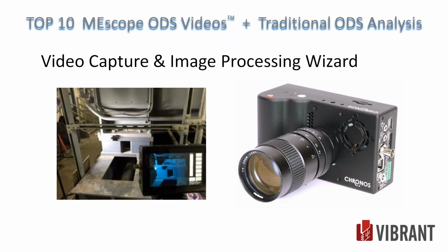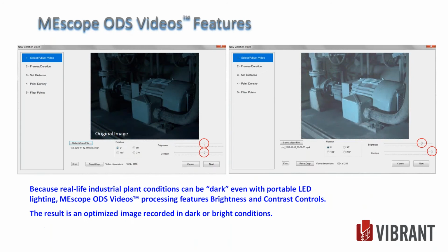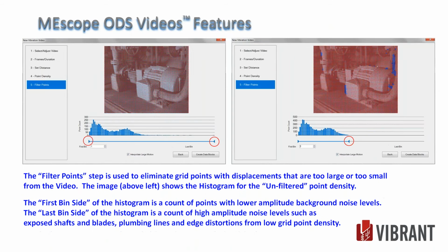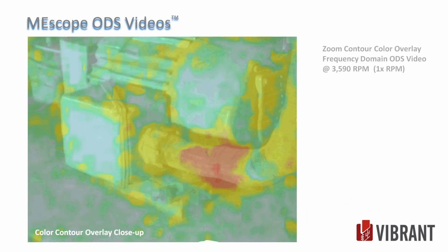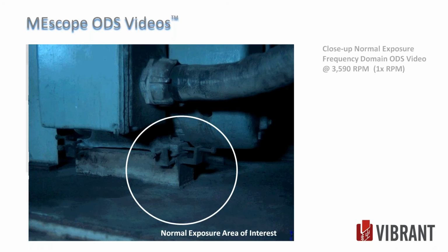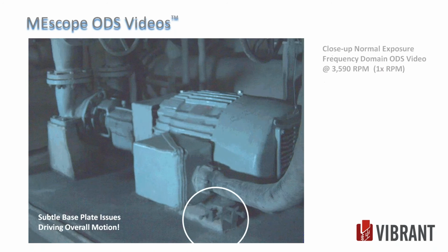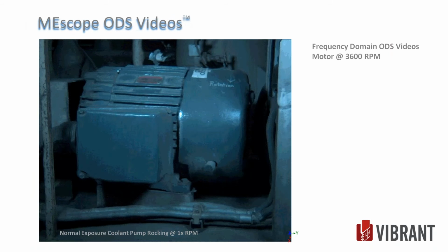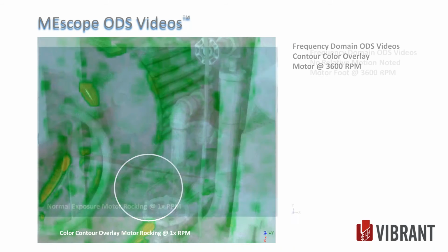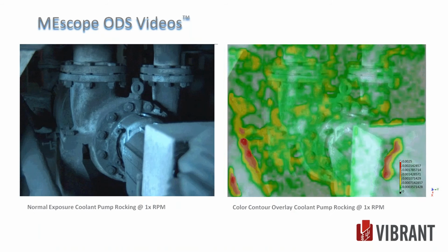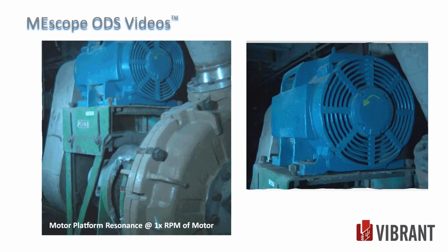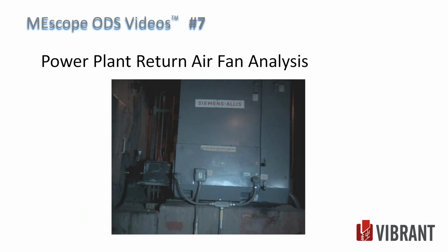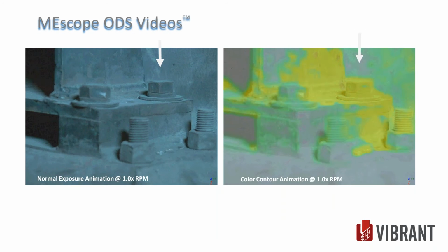Anything else, Mark? We had one comment. Christopher Rode wanted to explain the slurry pump with the cone. He said absorber. Of the absorber. Okay. He says that it sprays a lime slurry in the flue gas. If density gets too thick, it can cause a large imbalance and then clear out with a flush. Ours sits on a rubber donut mount, no fasteners. So he just wanted to tack on, since I think you were trying to explain it a little better.